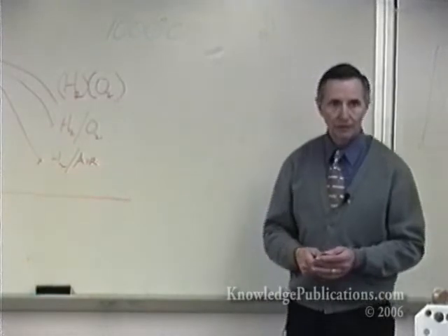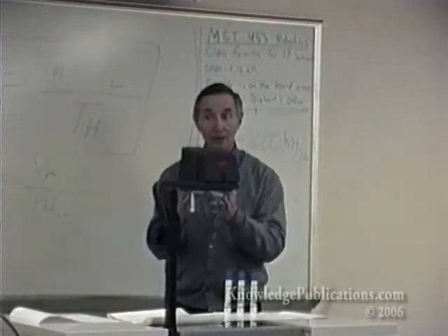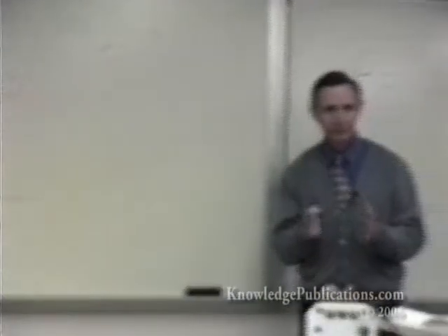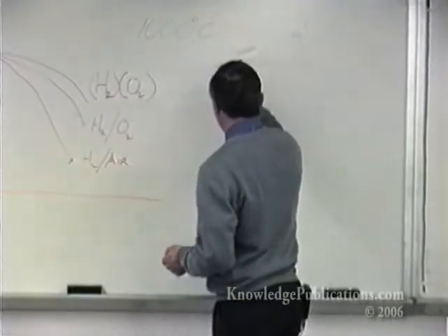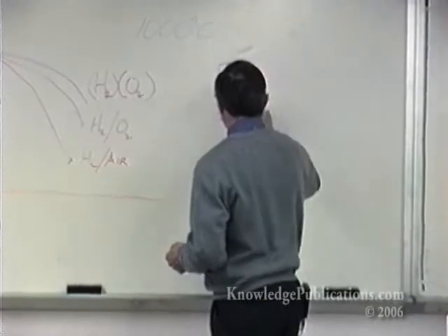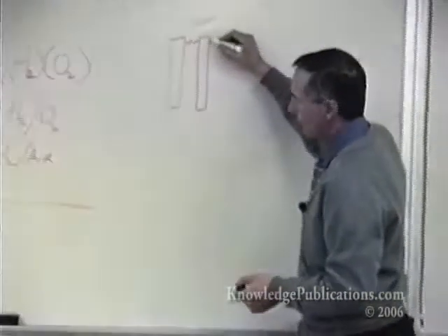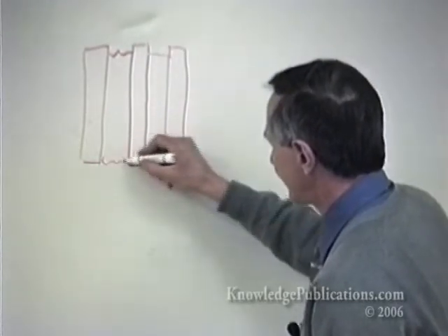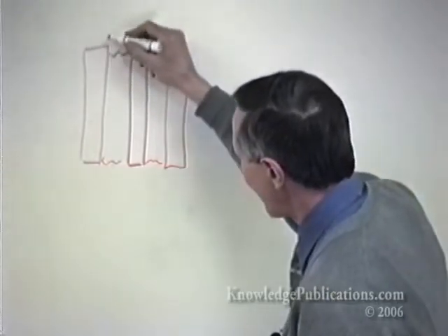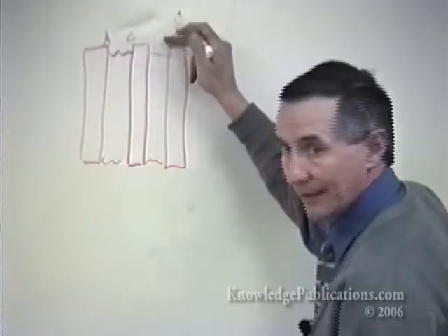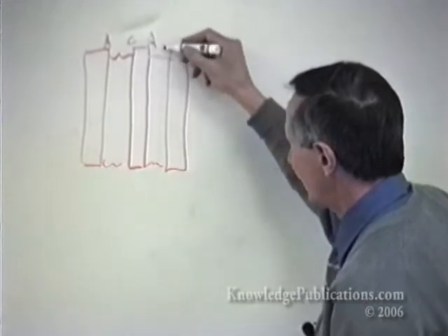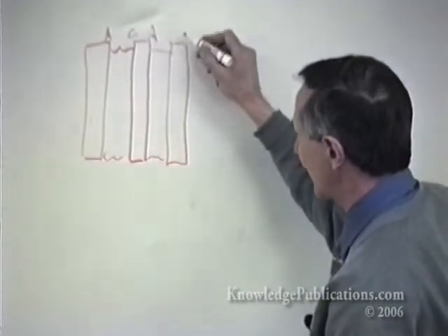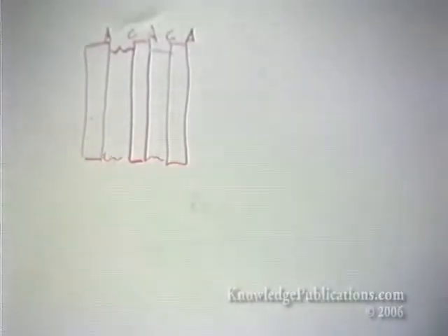But that would bring into question, would we do it with what type of series? Would we just build every one like this and then electrically connect them in series, or would we like to make it more compact by what is known as bipolar arrangement? In this bipolar arrangement, we'll make an anode, a semi-permeable membrane, a cathode, but we'll run one side of the cathode as the next anode. So we'll have an anode, a cathode, and on the other side of that very electrode, we'll make it into an anode. And across the way, we'll just do the opposite. We'll have it as a cathode here, and so forth, until we have added up the number of voltage units that meet our entire load requirement.